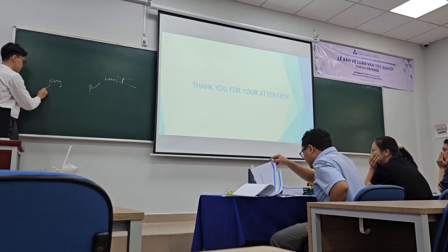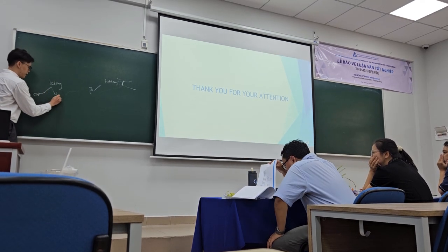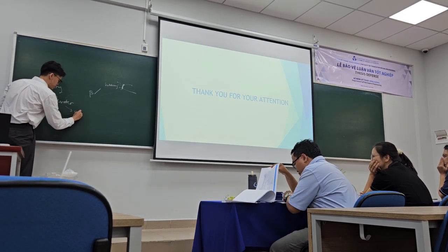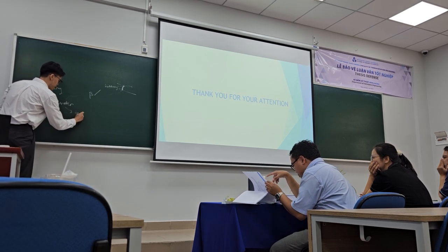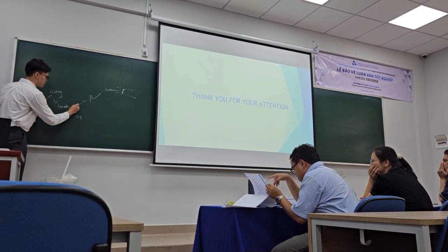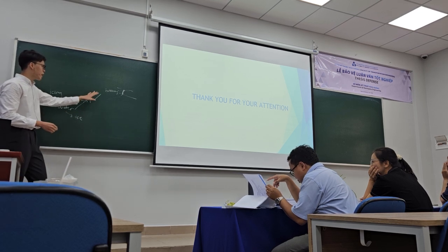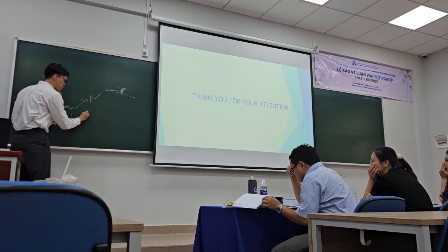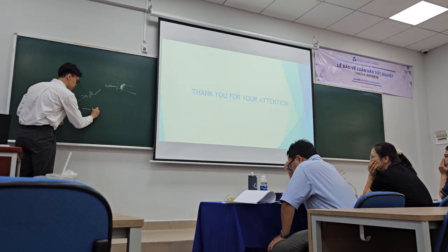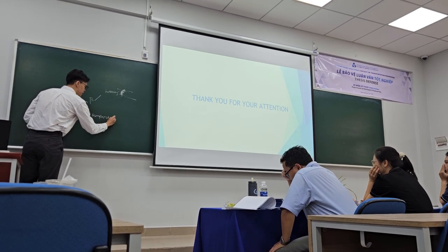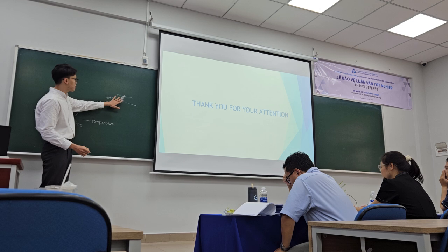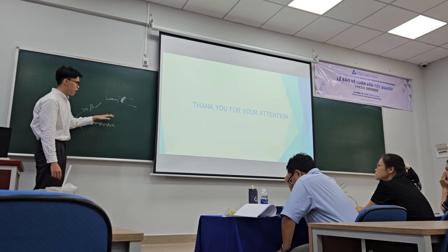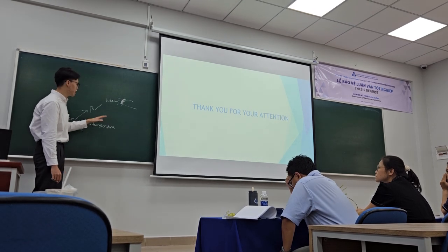have shown it in three stages. First, we saw the air phase. Second is water, and finally we calculate the ice formation. If the data collection is from this stage, it is just used to predict where the collection efficiency concentrates so much, and it will be combined with all the elements like temperature. Because if collection efficiency is higher, but the temperature of the airfoil is not low enough, or the temperature is high, it will not have icing on that.